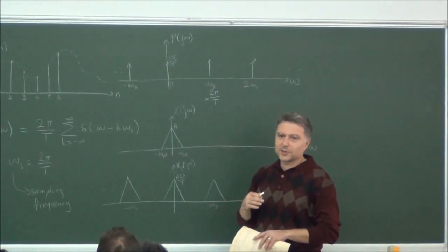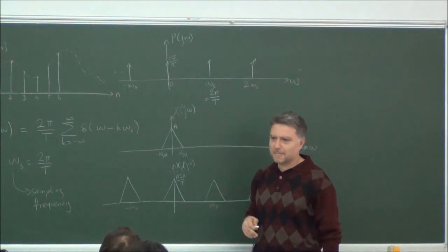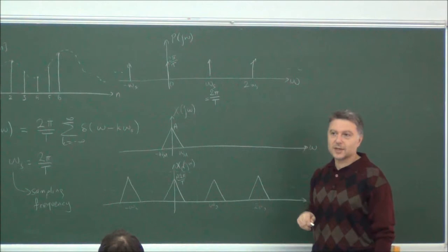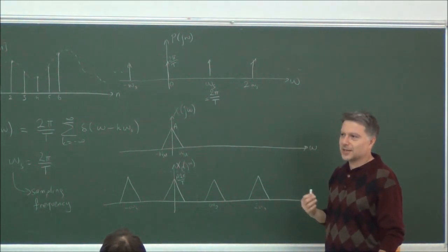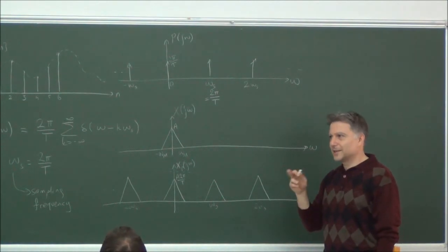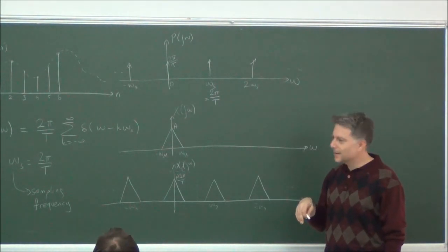What is analog to digital conversion? It is also simple. It is multiplication by an impulse train. And these two are inverse operators, inversions of each other. They are inverse systems, you can say. We have seen inverse systems, right? Is it invertible, I was saying. So this system seems to be invertible.